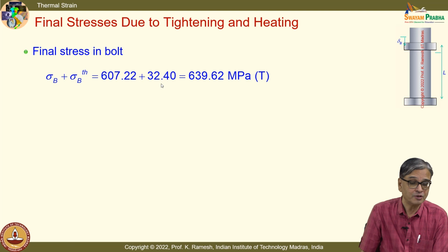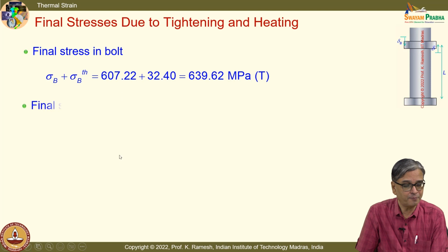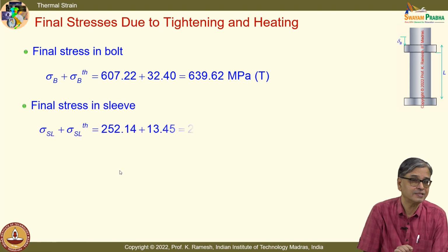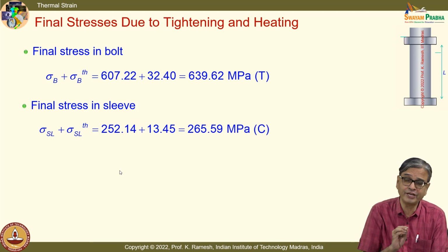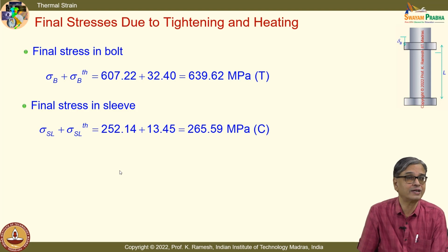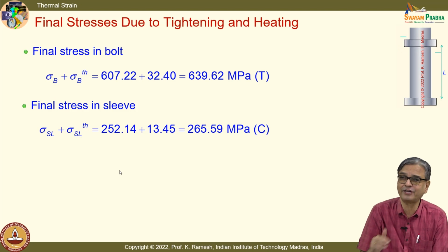So, you should not ignore it, even though the temperature stresses are reasonably small when you compare to the stresses due to tightening. The point here is, when there is a temperature change, additional stresses are introduced into the system. So, you need to have that estimated so that your design functionality is achieved. You should not have a failure.